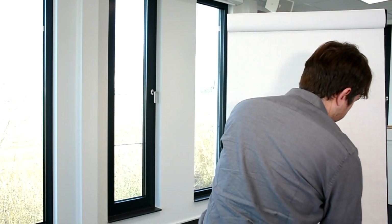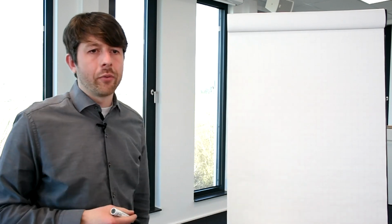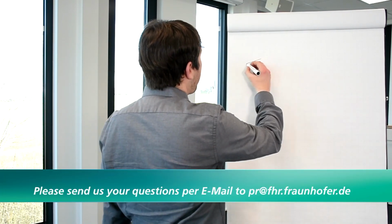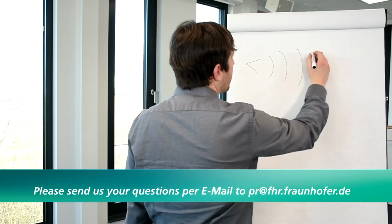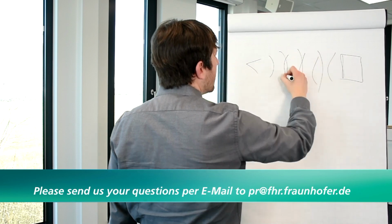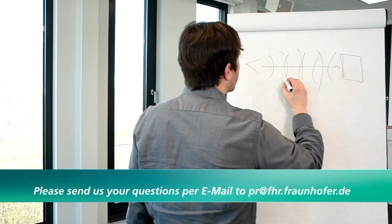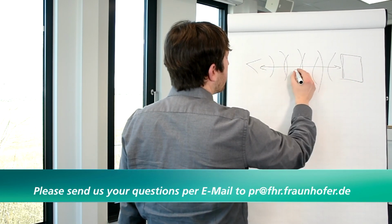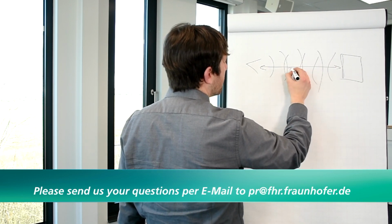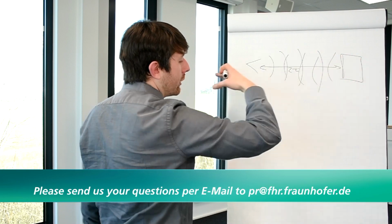The fundamental function of a radar is distance detection. If you have a single antenna transmitting a signal to an object, which is reflecting back, we have a certain time delay, tau, so practically 2 tau, because it has to go there and back.